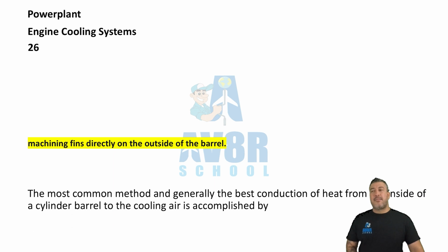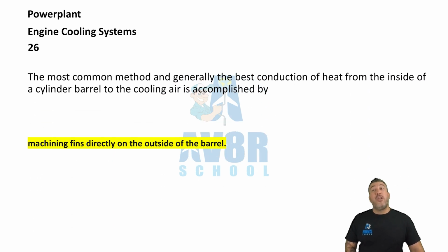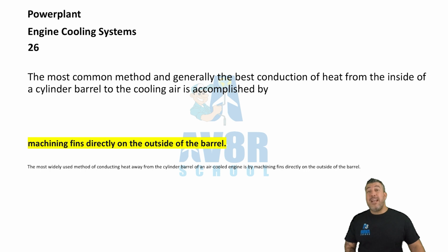Number 26, machining fins directly on the outside of the barrel. The most common method and generally the best conduction of heat from the inside of the cylinder barrel to the cooling air is accomplished by machining fins directly on the outside of the barrel.